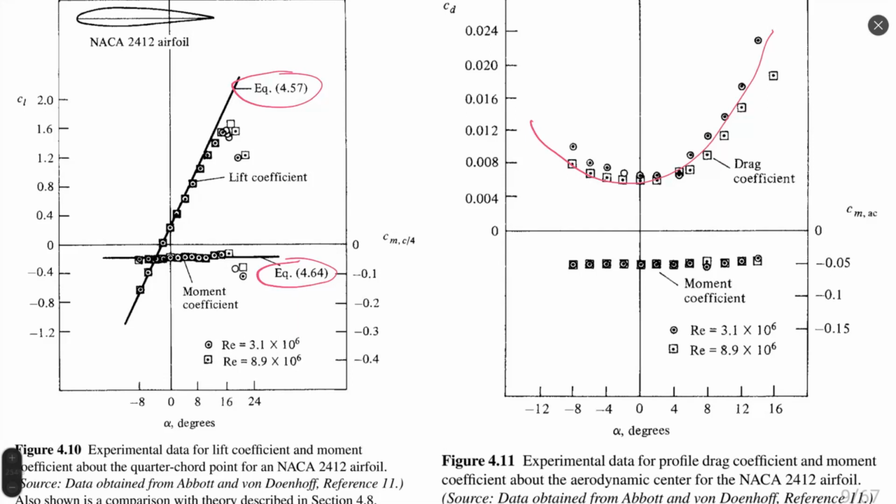But for the lift coefficient, we can do it, because the lift coefficient is mostly created by pressure distribution, and pressure distribution can be easily calculated through the Bernoulli equation and through the Laplace equation, as we saw previously, right? So we can calculate pressure, which means that we can elaborate the lift coefficient for airfoils, and the momentum coefficient also, because the momentum coefficient depends on lift, right?